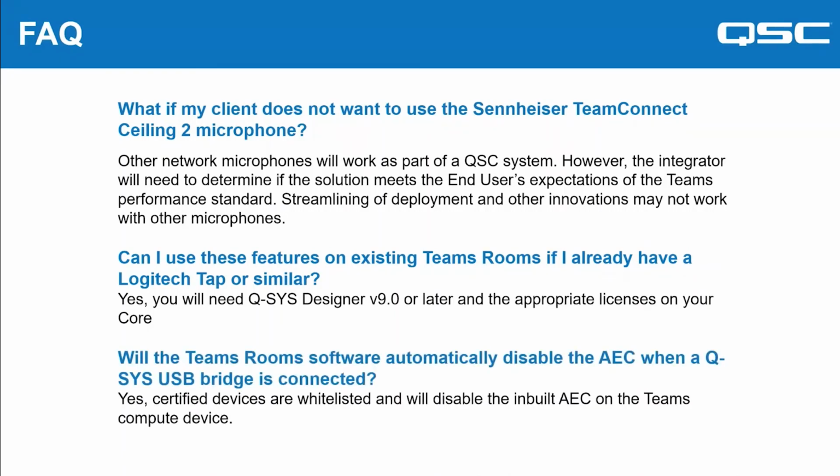And this is quite a hot topic for those of you programming DSP. If I connect to Qsys USB bridge, will it disable the internal AEC on the Teams Room PC? Yes, it will. So certified USB bridges, certified devices are what we call whitelisted. They're on a list of Teams devices that you can disable the AEC for, and that includes these Qsys devices.